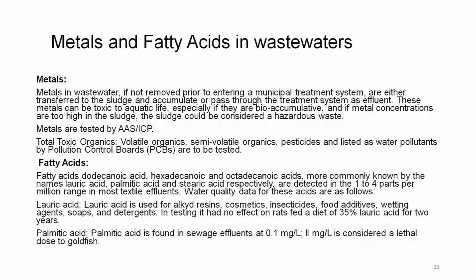Metals and fatty acids in wastewater. Metals in wastewater, we have seen, if not removed prior to entering the municipal treatment system, are either transferred to the sludge and accumulate or pass through the treatment system as effluent. These metals can be toxic to aquatic life, especially if they are bioaccumulative, and if metal concentrations are too high in the sludge it could be considered hazardous waste.